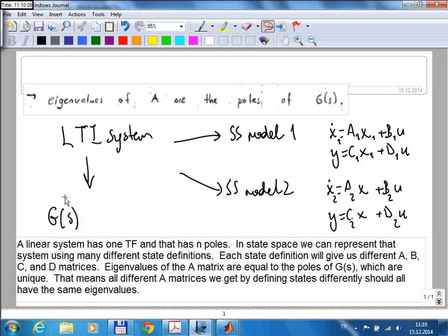We saw that what we do is we first calculate the poles, right? And then based on the poles we perform partial fraction expansion. And then from the partial fraction expansion we can calculate the response pretty easily. So at that point we saw that calculating poles has a direct effect on the response, because those poles become the response later on when we take the inverse Laplace transformation.